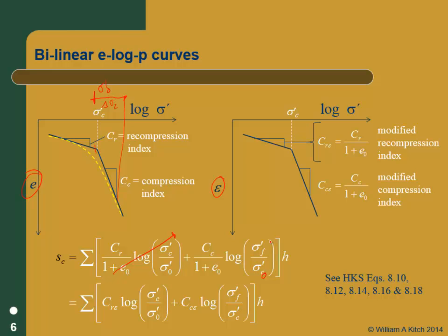And in those cases, we call that situation what? What kind of soil is that? If all the loading is on that virgin curve, it's not overconsolidated, it's normally consolidated, right? So this is normally consolidated. Now, what are the other 2 things that could happen?